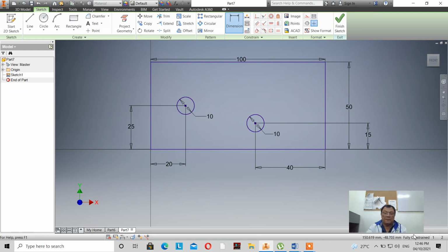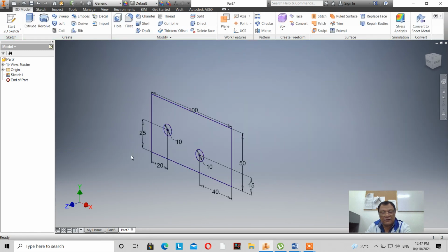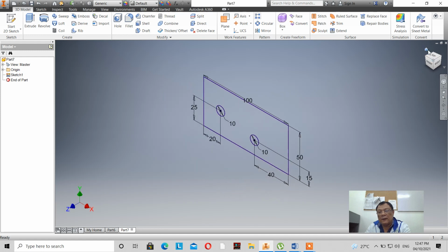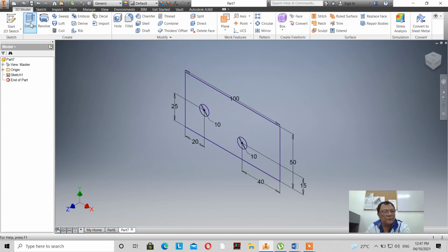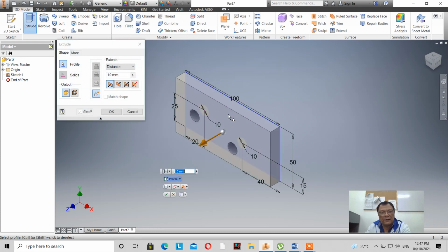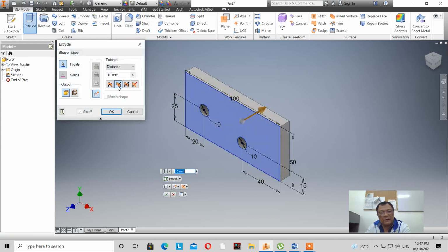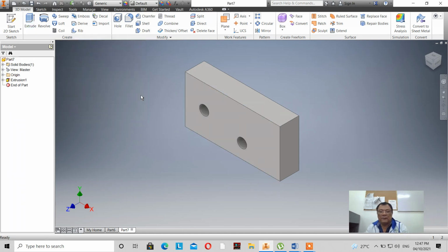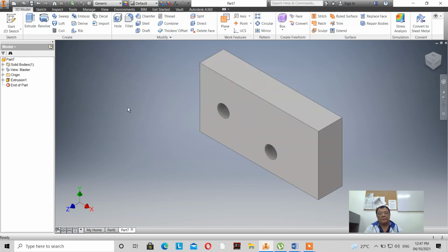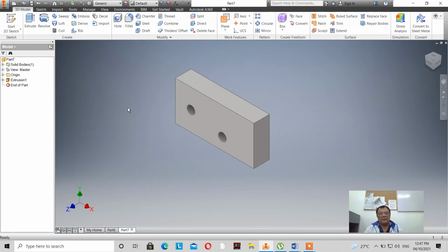Now you see my drawing is fully constrained. Okay? I'll try to take a look. When I click on the finish sketch, I have this one. Again, I'll go fixed distance. Now let me extrude this one. I will select that. I go on the opposite direction here, and then I will extrude it to a value of, let's say, 20. There you go. Okay.